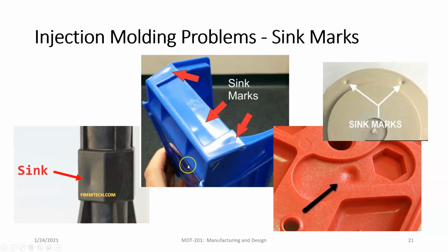And this is going to create what are called sink marks. So we can see those here. These sink marks are basically where the plastic, this bit, was the last area of the plastic to cool and solidify. And again, it depends on the application. It depends on the part, whether this is going to make it so the part is not usable or whether this is just fine.